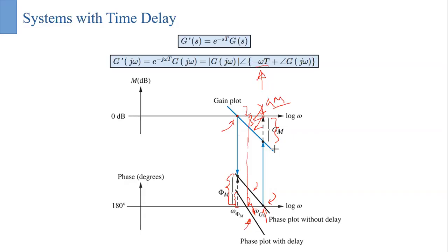So the delay element is not directly reducing the gain margin, but it is shifting our minus 180 crossing point, bringing it closer. Because of that, our gain margin is also reducing. What does it mean? The delay element will make our system closer to the unstable zone; it will be more and more vulnerable, and it will be trying to go into the unstable zone.